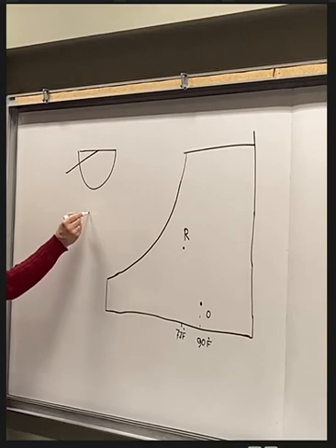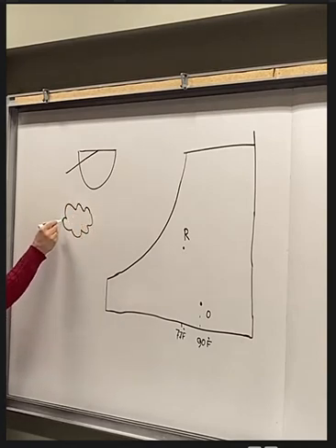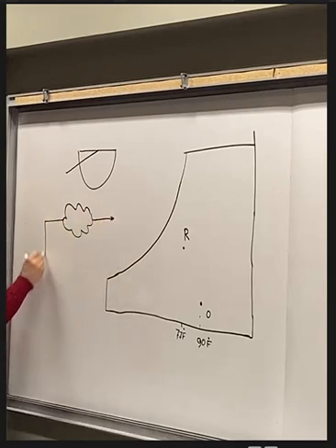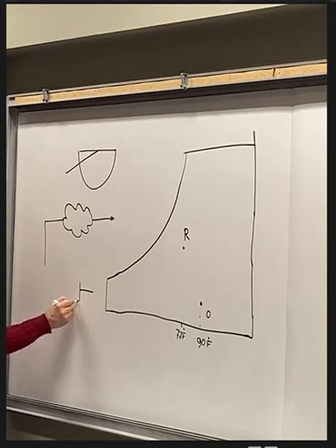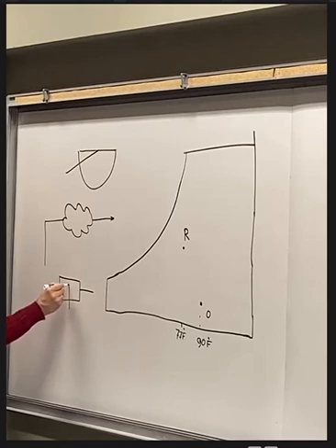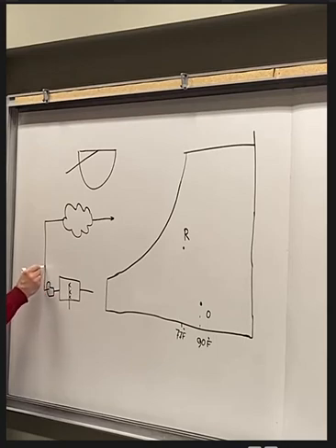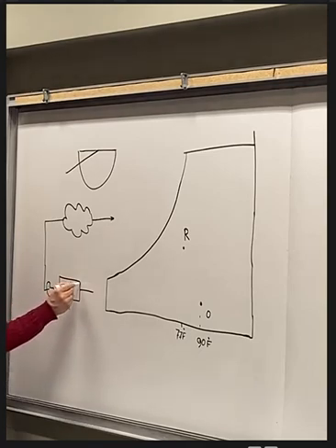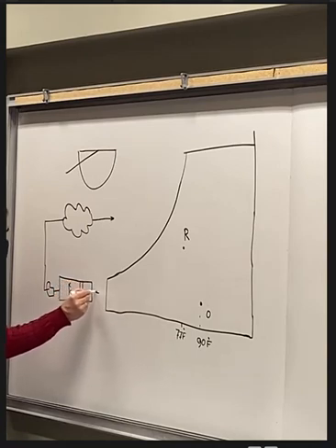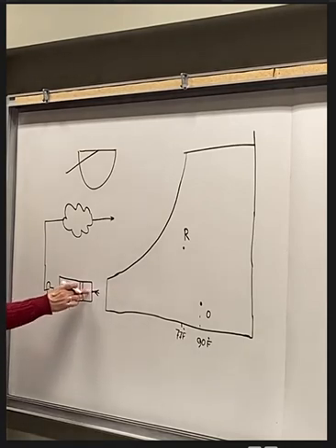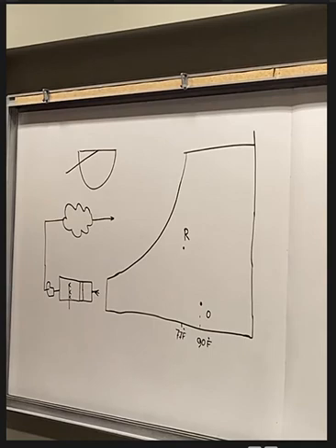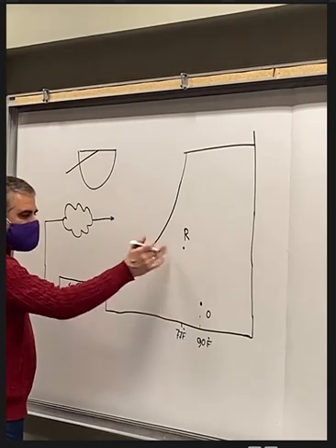So that means if we have a space, this is the exhaust air from the space. We can have fresh air coming to the air handling unit, and we can have an adiabatic humidifier. And then we have a fan that will be able to supply the air to the space. And of course, we have to install also a filter. So if we choose a system like this, very simple adiabatic humidifier with a fan and filter, most probably I think we'll be able to satisfy the design conditions of the space.